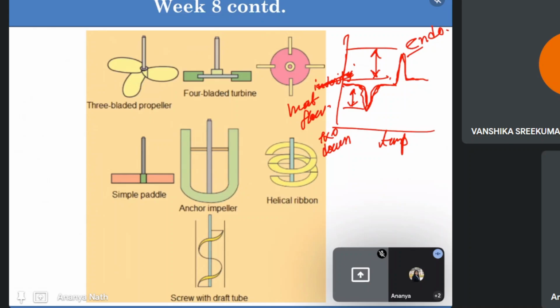Means, ma'am, at that temperature, there will be 50% of recrystallization. Means most of the grain has been recrystallized at that particular temperature, where heat flow is minimum. So this minimum heat flow means if there is a strain and we are heating it, then the strain energy is being released in the form of heat.